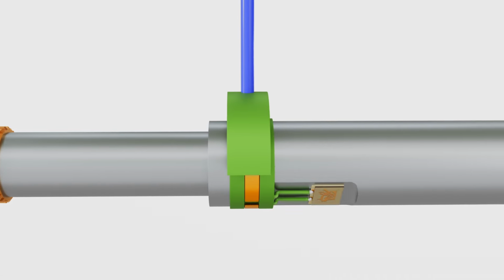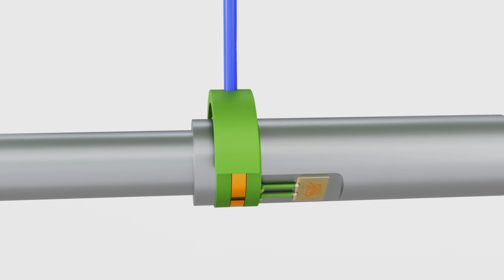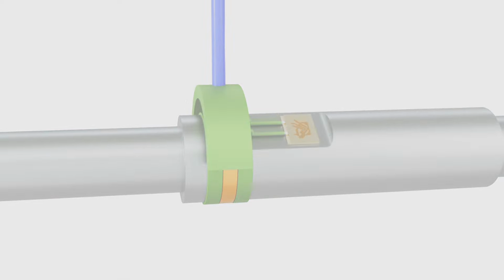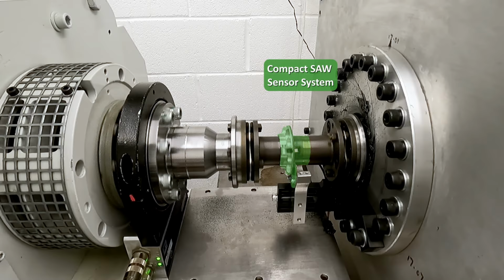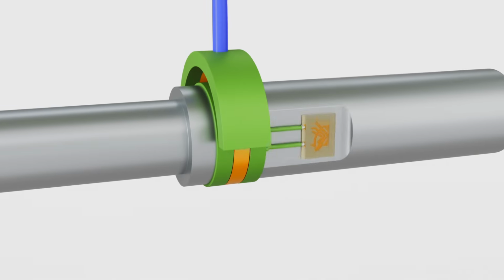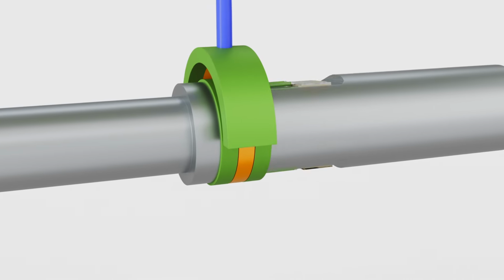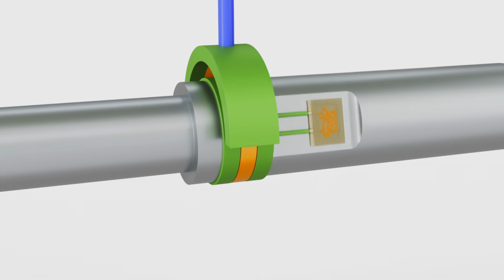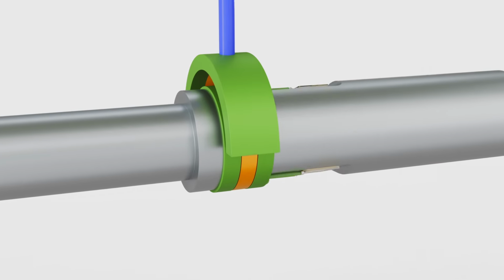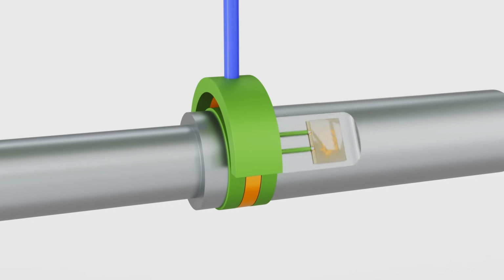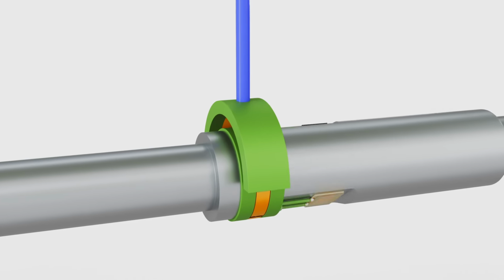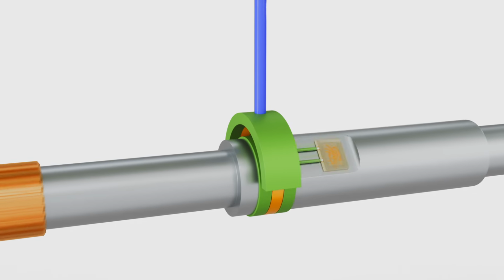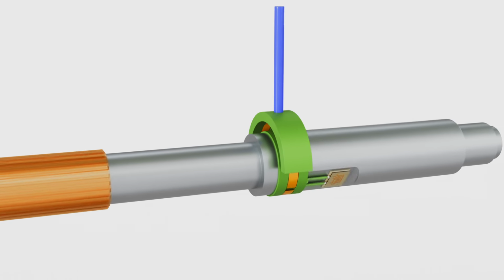The reader creates an interrogation signal which is transmitted to the rotating shaft through the RF coupler. The SAW sensing elements on the shaft do not require any other power source and work as a passive backscatterer, reflecting the interrogation signal back to the reader. The backscattered signal's frequency of oscillation is affected by the physical measurements such as strain and temperature. The reader analyzes the received backscattered signal and calculates the value of the strain and temperature measured. The shaft surface strain gives us an accurate measurement of shaft torque.